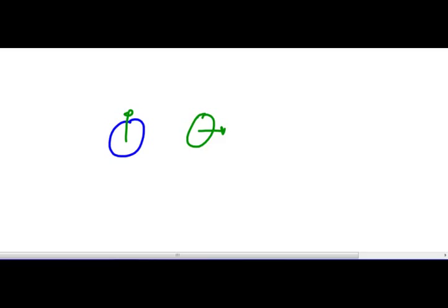Now, our current printers are using a stepper motor to get the ink from one side of the printer to the other. That's how I'm doing that. That's how it knows it's here, and here I'll show you, here and not there. Because the stepper motor is moving it, the stepper motor is going to get it to the right spot every time. I count 10 steps, it moves 10 steps, period, the end.